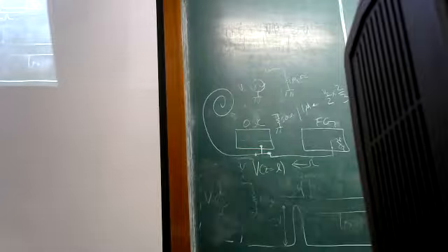Currently, it is set to matched load setting. So it actually gives you the value of what is going to be dropped, which is actually V0 by 2. So V0 by 2 is 1 volt. But when I connect a 1 mega ohm, it will measure 2 volts. But I can change a setting here, which will actually not change anything to the voltage. It will just change the display to 2 volts. This is just for bookkeeping purposes so that you keep track of what you're doing.